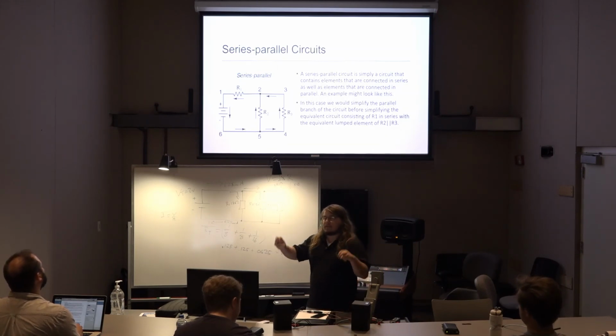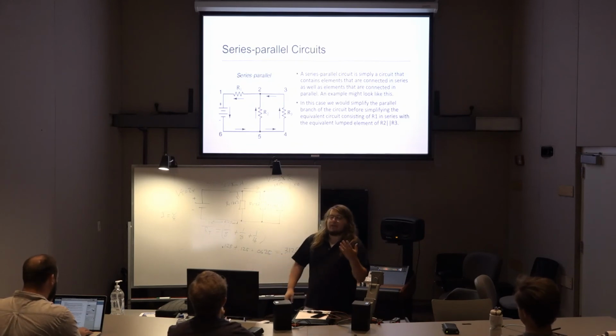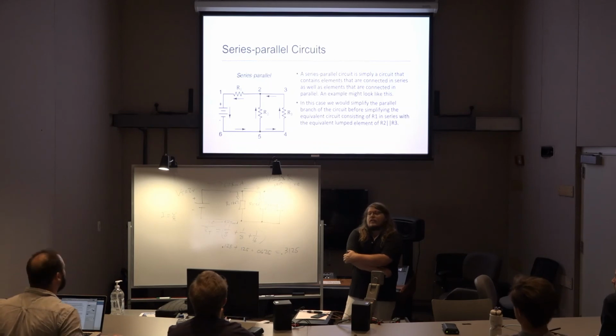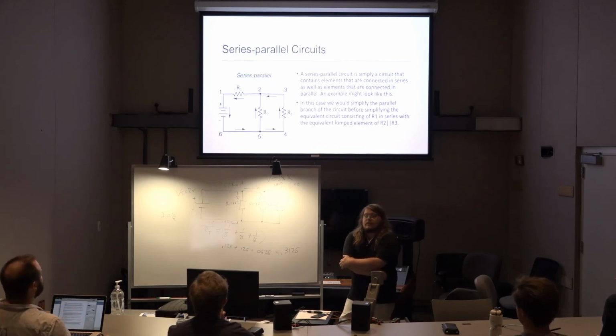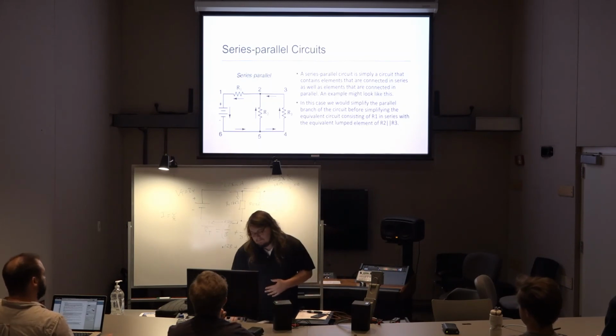That big resistor, smaller actually, as we know, because of the parallel relationship, would then be in series with the first element. We could figure out the total resistance, we could figure out the total current. So, series parallel, we're just combining them.